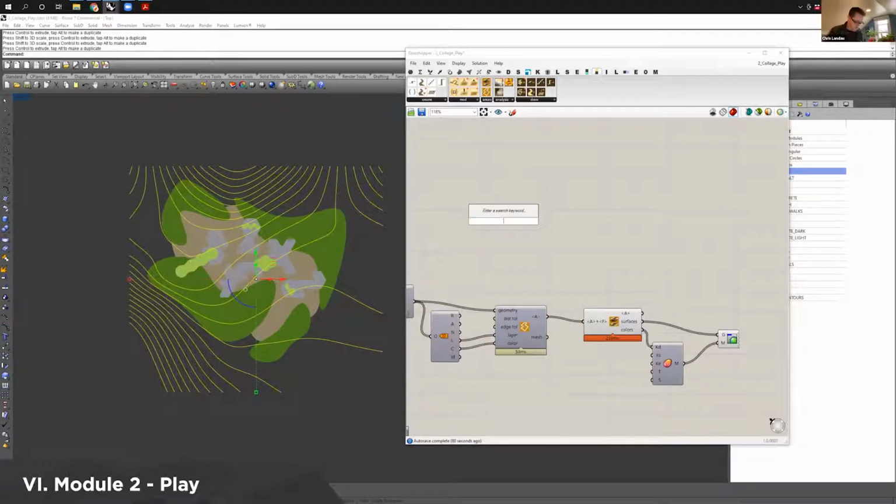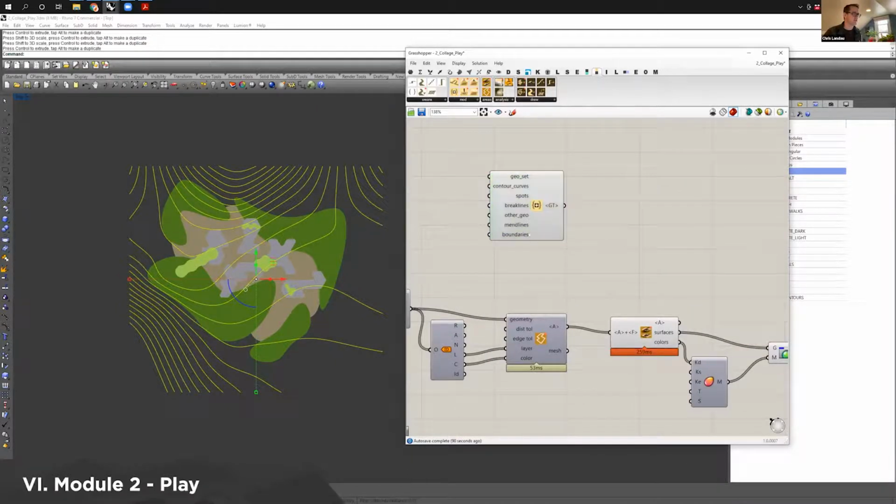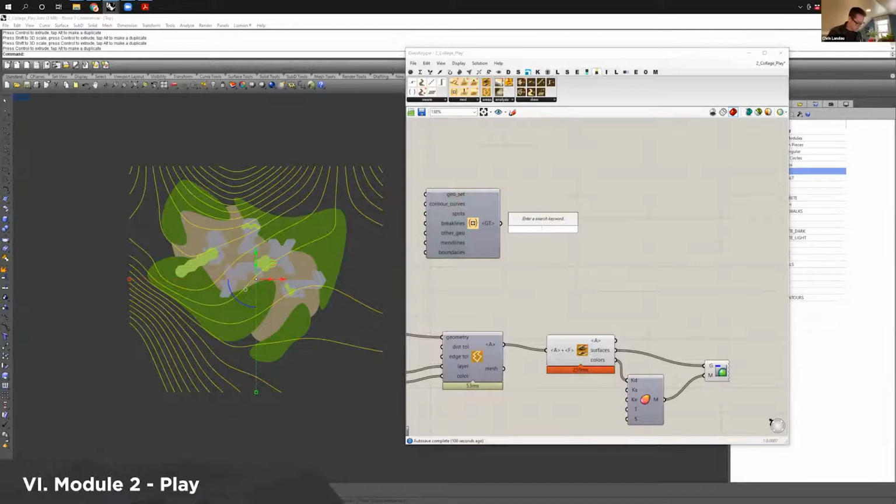Then we can do, I'm doing this really fast, we can do an add to geoset. And this lets you directly input things. So I can literally not even create a container and just do a right click and say set multiple curves right into there. And now it's referencing those. And then I just do create topo,